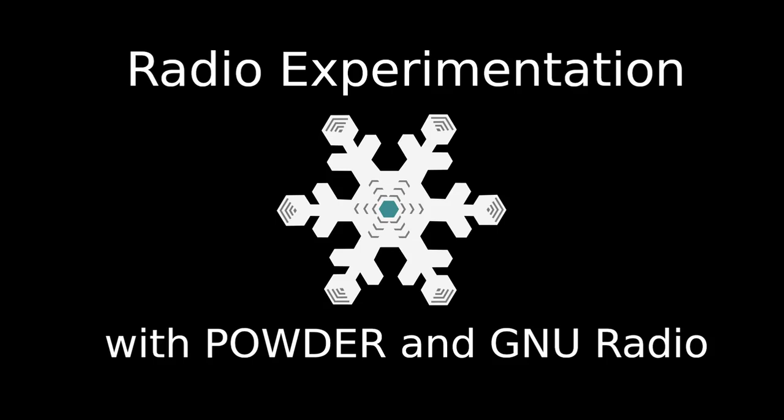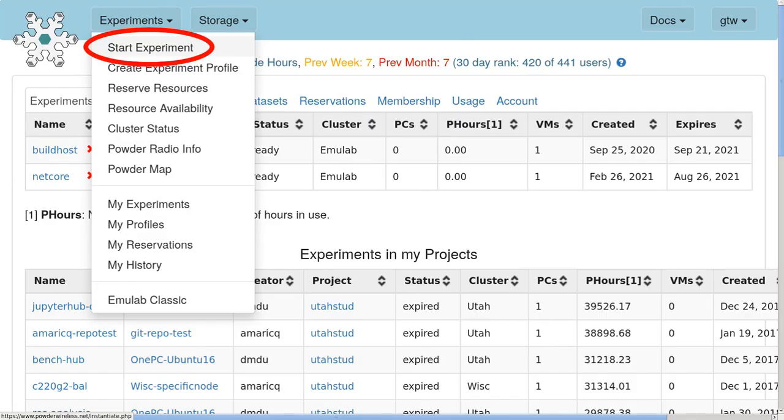Hello, I'd like to demonstrate how to use Powder to conduct a simple experiment showing communication between two software-defined radios using GNU Radio. With a Powder account on powderwireless.net, you can follow along and try the same thing. Log into powderwireless.net and choose Start Experiment from the Experiments menu.